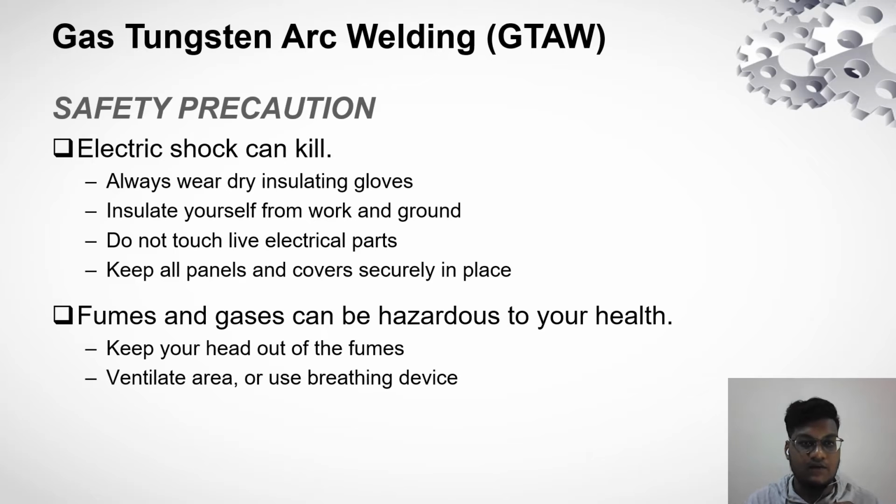Okay, now we look at safety precautions. Electric shock can kill. We should always wear dry insulating gloves. Insulate yourself from work and ground. Do not touch live electrical parts, and keep all panels and covers securely in place. Second one is fumes and gases can be hazardous to your health. Keep your head out of the fumes. Ventilate area or use breathing device.